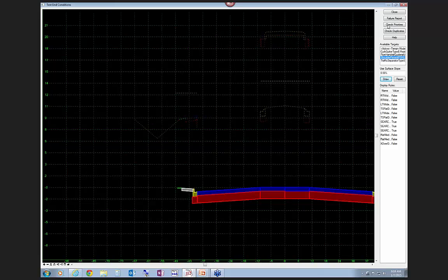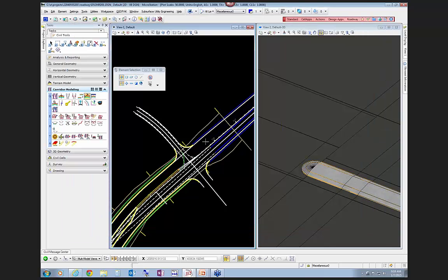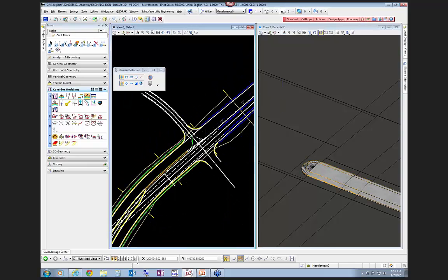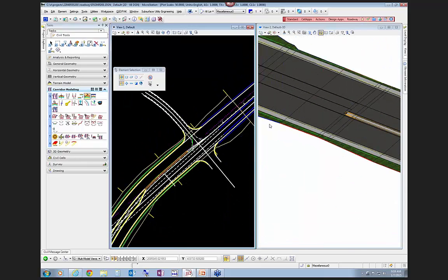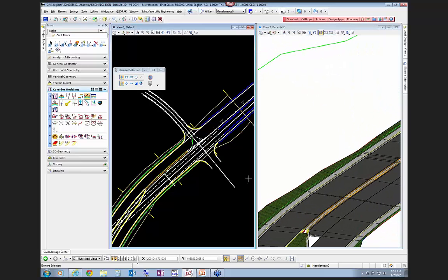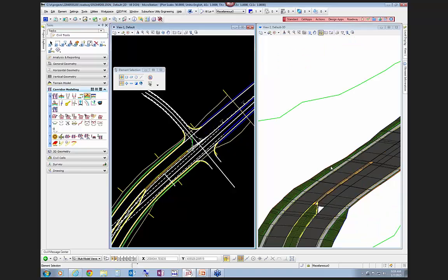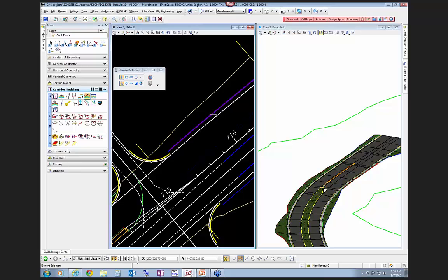And then if you look at applying it on your template, you do a file save here, and then I close out, you'll see that I've got this type of situation here where actually this curb and sidewalk goes all the way through this. I'm looking at this intersection right here where this traffic separator is around this curve, and you notice that my corridor stops here. And I do have a shoulder situation over here.